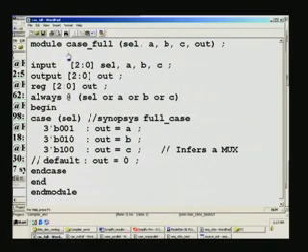and the program is quite simple, and what we have here is 3 inputs A, B, C, and one select pin is also there. It is basically a case implementation, and Synopsys, this is the special thing which I have mentioned earlier while dealing with the RTL coding guidelines. That is, after the comment you use Synopsys, then space, then full underscore case. This is a reserved word here, although it looks like a comment. So, you cannot put a comment which resembles this, or instead of this you cannot put a parallel case also. So, 2 are reserved.